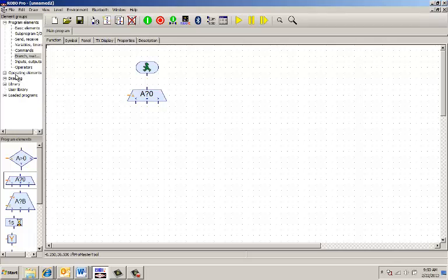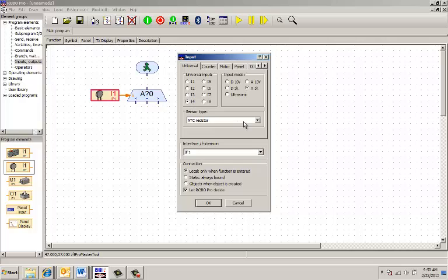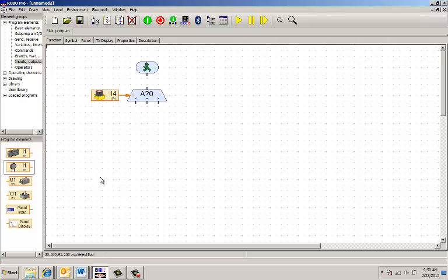Alright, and so what I'd like you to do then is, in inputs and outputs, we can actually tie a variety of elements in here. So this is a universal digital input, this is a universal analog input. So if you'll connect this there, remember that A is tan, so it needs a tan object connected to it. Right, and it says I1, so I need to change that to I4, and I need to change it to the type of sensor I'm using, a photoresistor. When I do that, the input mode here will change automatically, so I'll say OK.